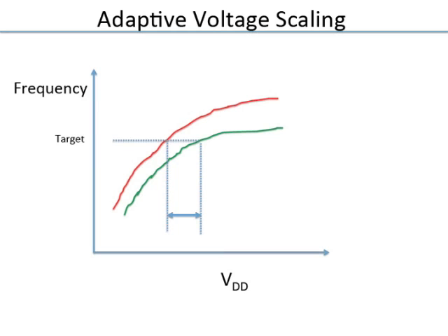That is adaptive voltage scaling. So how do you do that? Maybe you have a way to characterize each chip when you do testing. The simplest way used to characterize is a ring oscillator. You put in a ring oscillator and measure its frequency. If the frequency of the ring oscillator is high, you say it's a fast chip. Then you program a different voltage setting for that frequency.